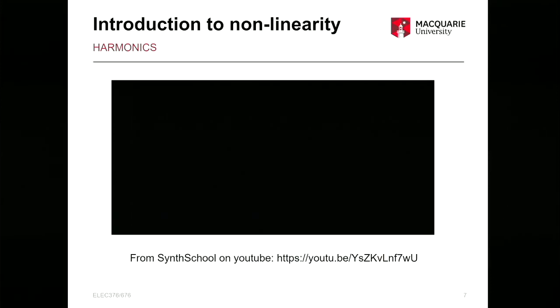So we are basically looking for a system's response with a single sine wave input. We choose the sine wave because that's the simplest waveform. It has only a single frequency. That's the purest wave that we can have. If you take a square wave and put it as an input to the system, because the square wave has multiple frequencies starting from the fundamental to quite high frequencies, the system responds to different frequencies in a different way.